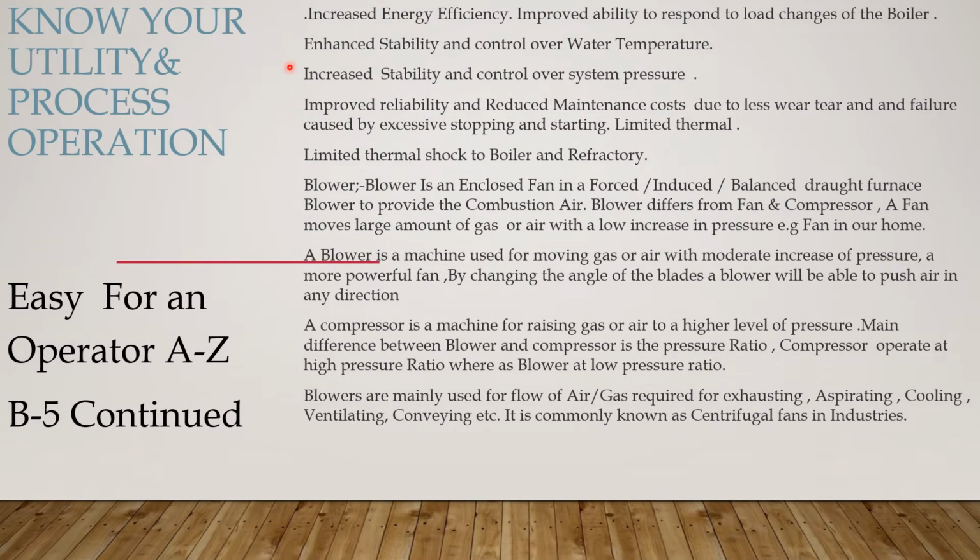Now I can see the benefits of the burner turndown ratio. It will increase the energy efficiency, that is, improved ability to respond to load changes of the boiler by means of a fuel gas turndown ratio. It enhances stability and control over water temperature, increased stability and control over steam pressure,